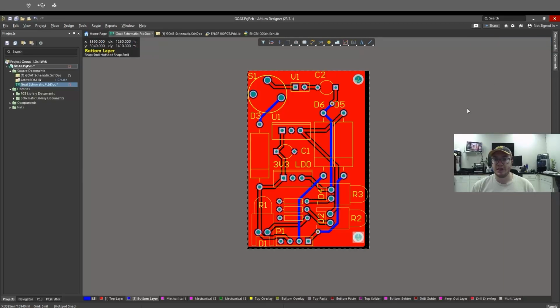And why we want to have these is so that when this gets compressed onto your board, we make sure that it stays very well connected and it's completely constrained. Because if it isn't, and it flies off for some reason, your whole payload loses power. That's bad. So it's very easy to add mounting holes. It's a great way to just make sure everything's taken care of. And now we're going to add some labels.